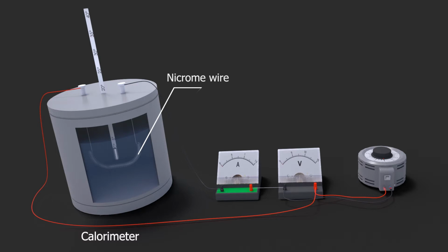Increase voltage across the wire by the variac, and connect an ammeter and voltmeter to measure current and voltage. Set the variac scale to adjust the voltage and current value of the nichrome wire, and current is passed through periodically, and measure the heat quantity from the nichrome wire. There are indications of voltage and current. If voltage, current and time increase, heat quantity will also increase.